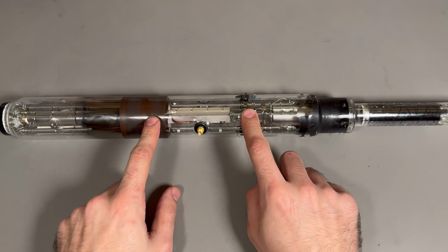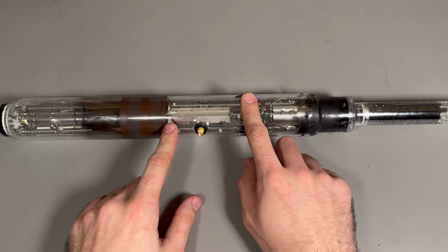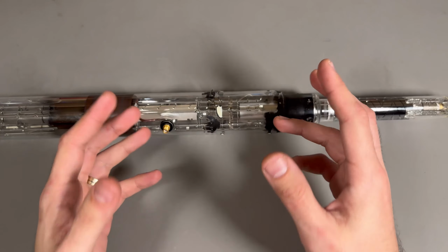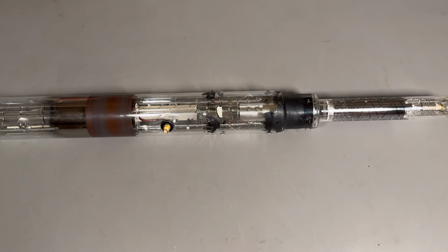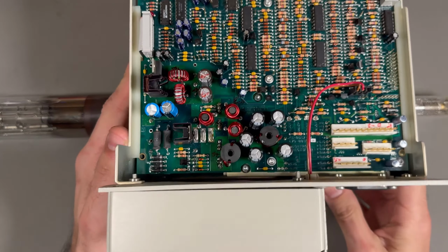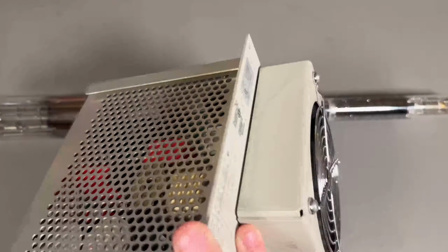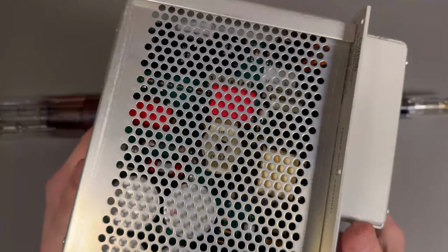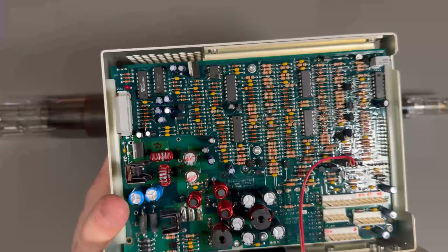What's the story of this one? Well, the first SCD5000 that I got off of eBay with the help of a very dear friend, this is completely dead. So the SCD5000 had a broken power supply. It's this beast over here, and it's an enormously complicated power supply. It has lots of fail-safes and stuff like that, and it's the same power supply as in the 1100 series of scopes. Might do a video about it because it's a very interesting switching power supply. It's a current mode controlled switching supply, and it's got all sorts of protections.